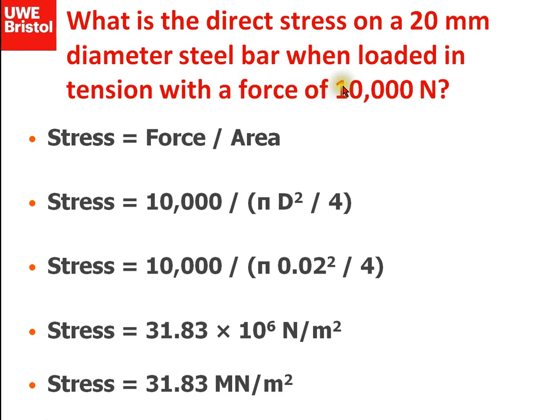Notice it's far better in fluid mechanics and also stress analysis, if you're given things in terms of the bar's diameter or the tube's diameter, to stick with using diameter and use this formula and not pi r squared. Use pi d squared divided by 4 for your area.